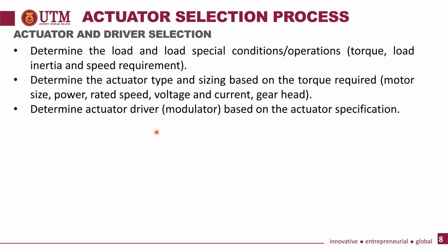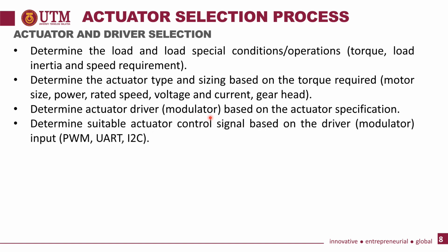It is like the middleman between the supply and the motor. It will process all of the related things, PWM, and also the direction of your motor. The modulator will do that. And then next, you need to determine the suitable actuator control signal based on the driver.